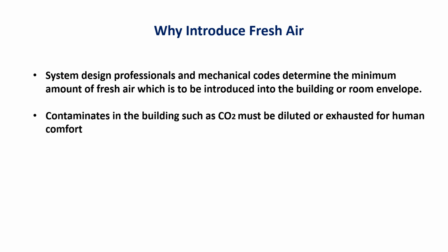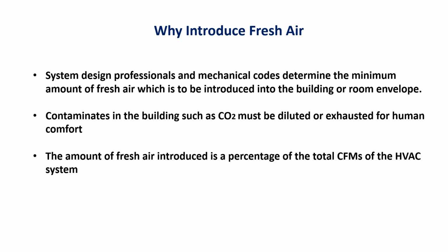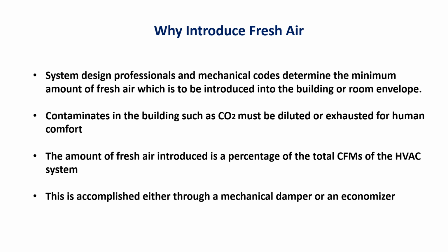Contaminants in the building, such as carbon dioxide, must be diluted or exhausted for human comfort. The amount of fresh air introduced is a percentage of the total CFMs of the HVAC system. This is accomplished either through a mechanical damper or an economizer.